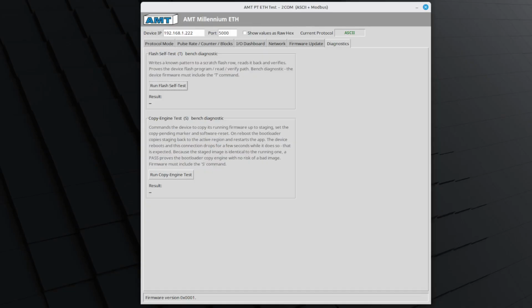The same analog, digital, and pulse values read straight from the Modbus registers and coils. It is a quick way to confirm the Modbus map before the unit goes on to something like a PLC.